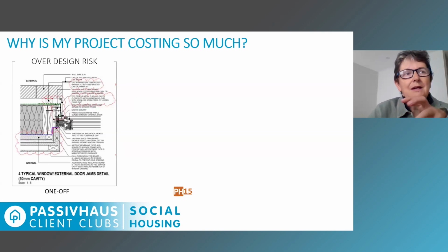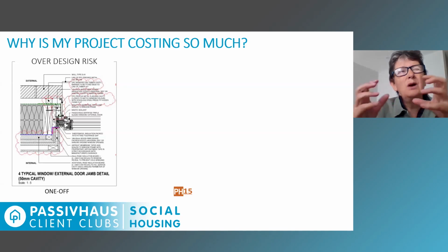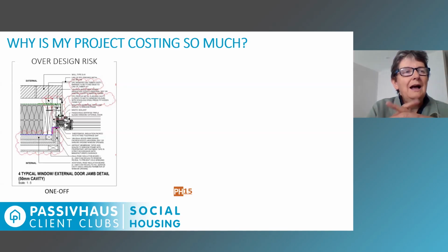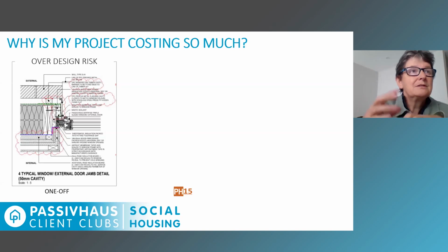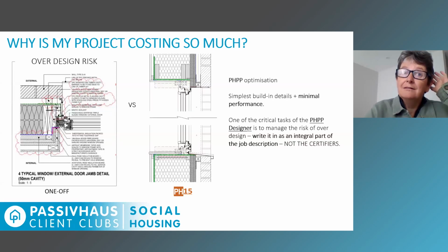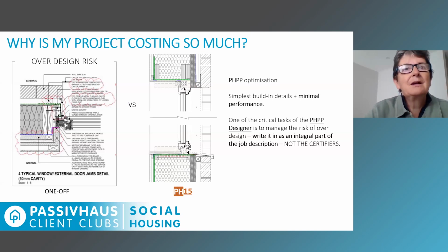What they're trying to do here is reduce the thermal bridge, where there's a very weak point where windows join walls, and they've really gone to town with it. They're over-insulating the frame inside and out. There's lots of layers going on, and they will have got a very good psi value for that detail, but it's very much a one-off detail.